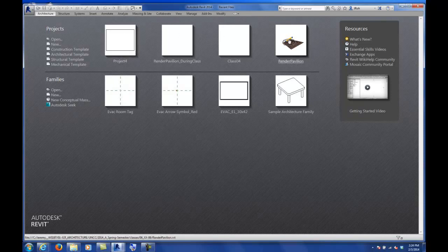The project environment, this is the main unified model where you will be working. And basically the way Revit works is you eventually bring in certain components. So if you're familiar with SketchUp or Rhino, in SketchUp you have components, in Rhino you have blocks, or in AutoCAD you also have blocks. Those are similar to families, and these are single one-off objects that can be parametric that come into the project environment and you place them in your model. Both of these environments have different ways of working, and we'll get into that.